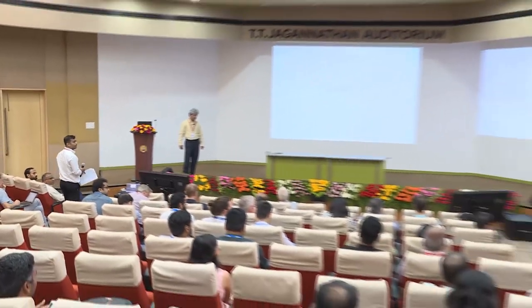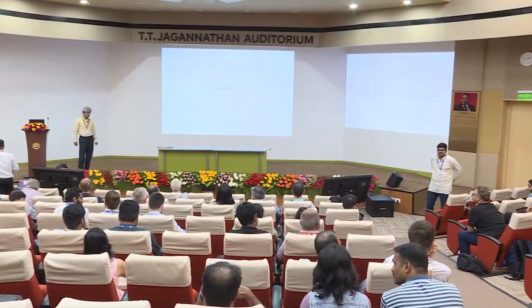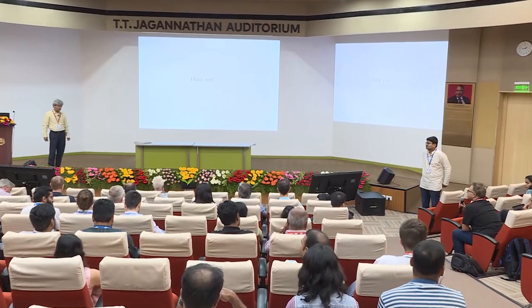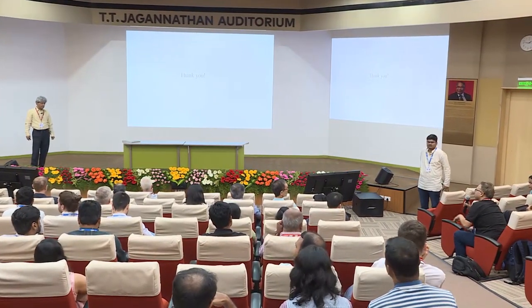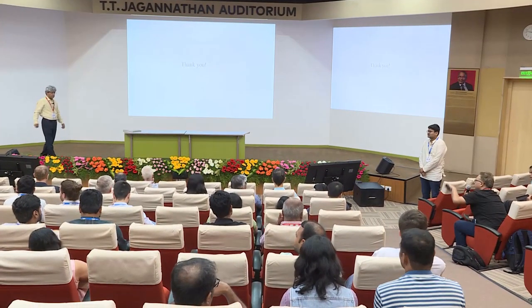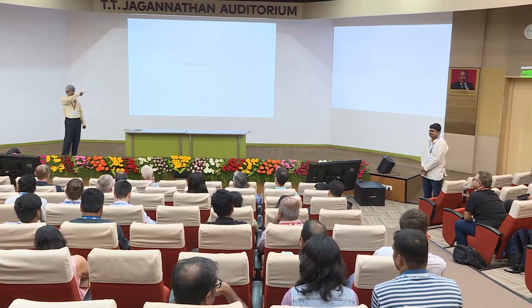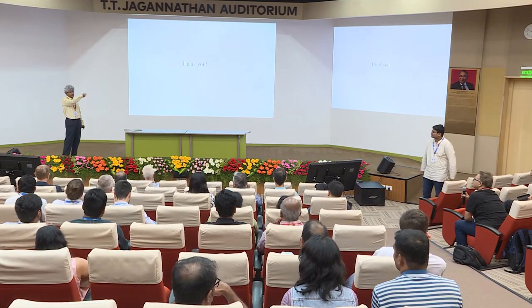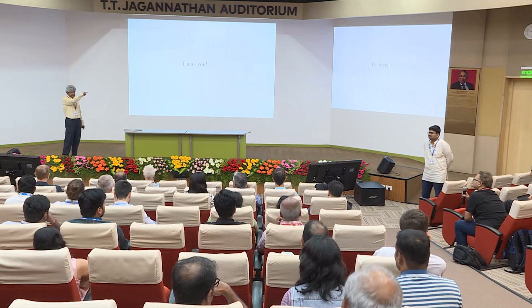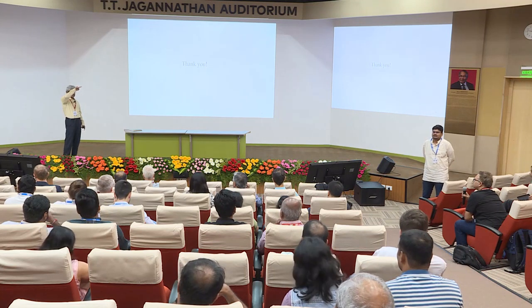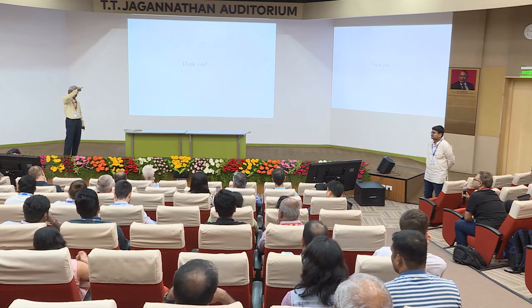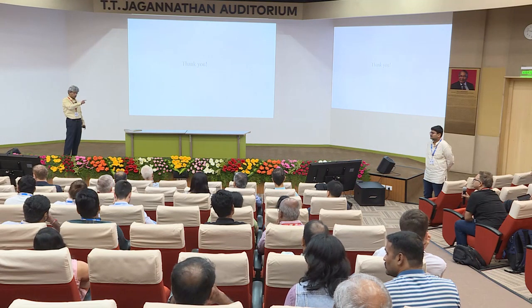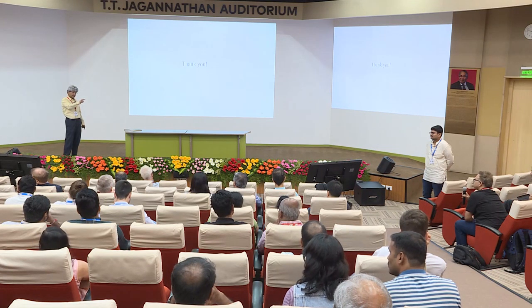Thank you for the interesting talk. How do you model the contact angle for the pillared surface? Because there you will have to impose the contact angle boundary on the vertical wall of the pillars also. Right, yeah. So you have to keep track of the contact line as it goes over the surface, gets pinned, and then starts moving down the wall, and then after some time reaches the lower wall.